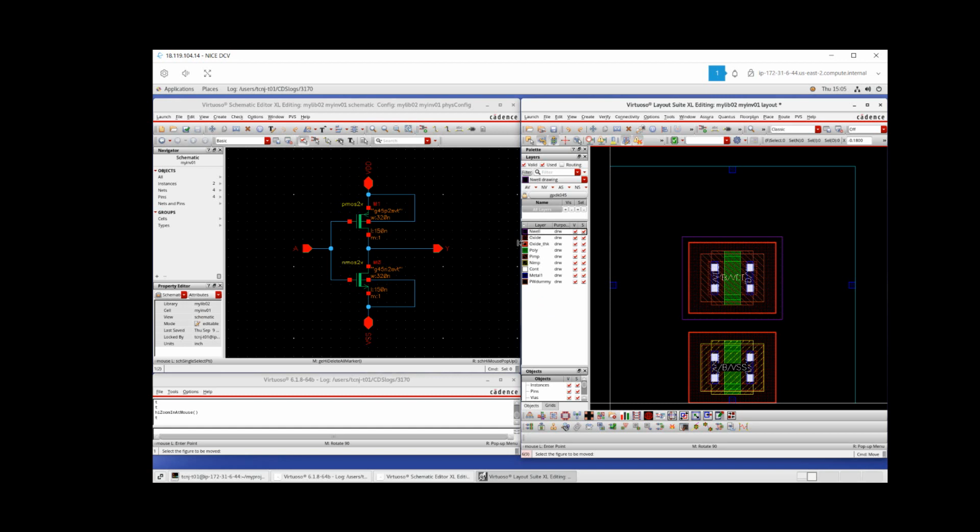So we can just go to stretch and select, or actually, we cannot stretch that well, because it is part of the transistor. It is hierarchically inside the transistor, so we cannot really edit it. It's a part. What we have to do is add or draw endwell.